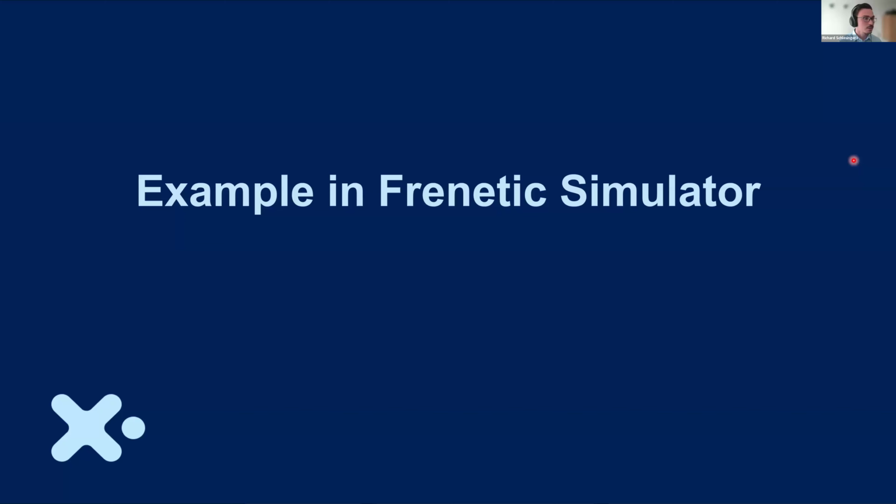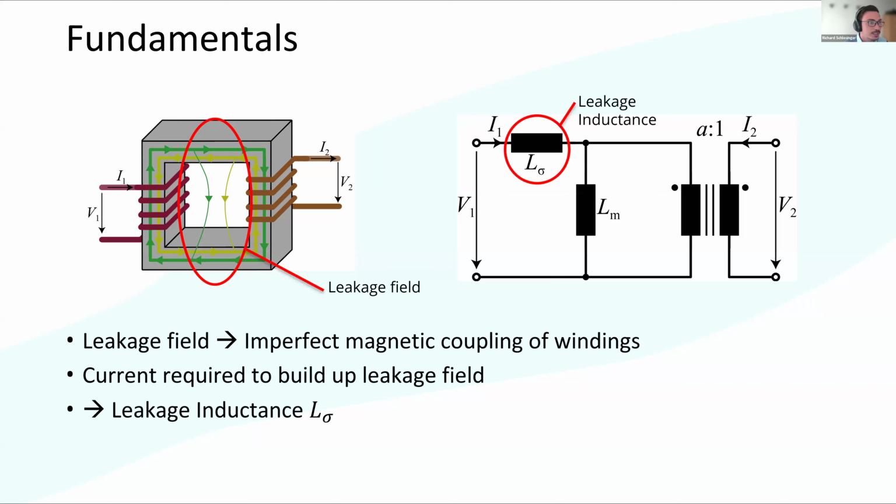Yeah, of course. Well, basically, you can never ever measure leakage inductance directly. Maybe I explain this with the equivalent circuit. Here, basically, how you measure leakage inductance is always from one side: you excite the winding with a current and you short circuit the other one.